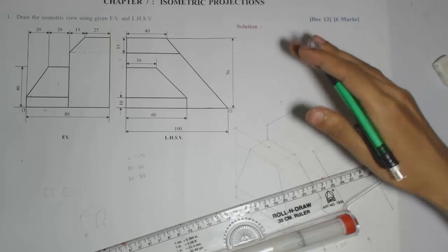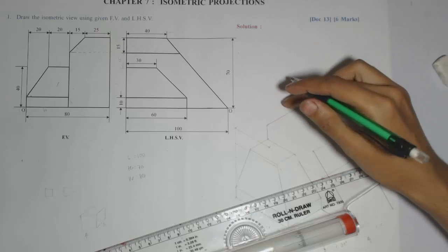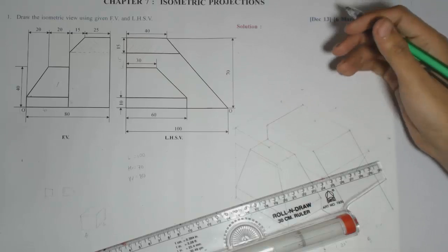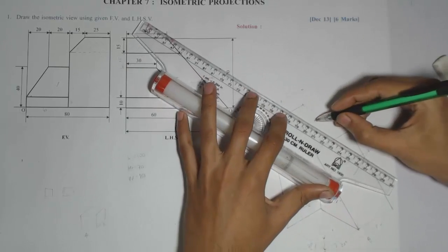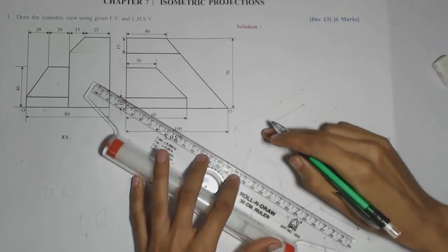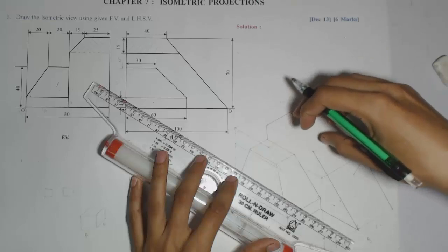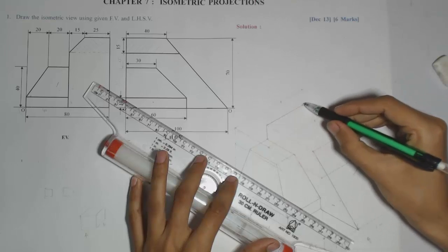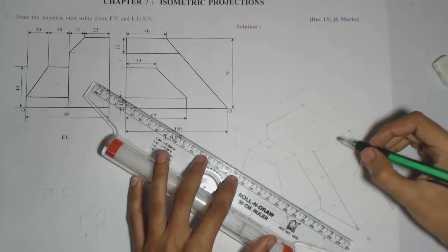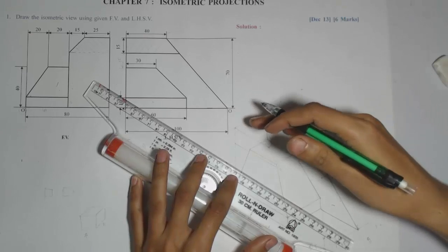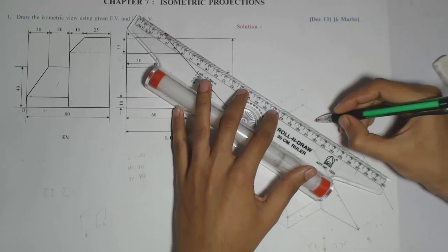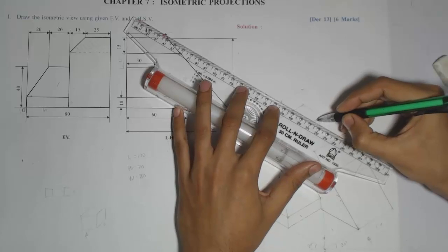Now since it is the highest top view, nothing is going to come above that, so it will be entirely visible to the observer. So I can make it dark, which we could not make for the previous top view, because some part is resting above that top. This was the previous top view, but I'm not sure whether I should make it dark or not, because some part will be resting above that, but on this top view nothing will rest, so I can make it dark.